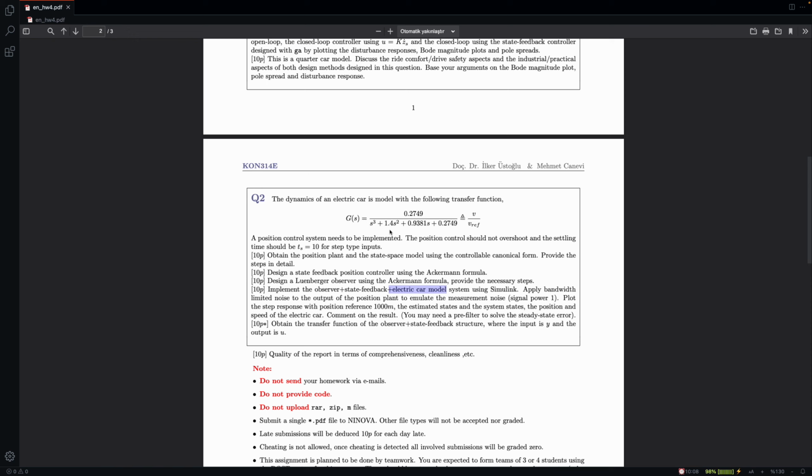In that case, of course, you will not be able to look for the system states and the observer states and compare them. So what you should do basically at this point is maybe use another Simulink model where you just compare the states of the whole system, where you have two state space models probably, and compare the states only. And in your final answer, where you provide basically the necessary stuff from here, you use the transfer function here. So we want to see this transfer function in the resulting Simulink model, but if you need, you can just use inner copy, convert everything into state space and compare them.